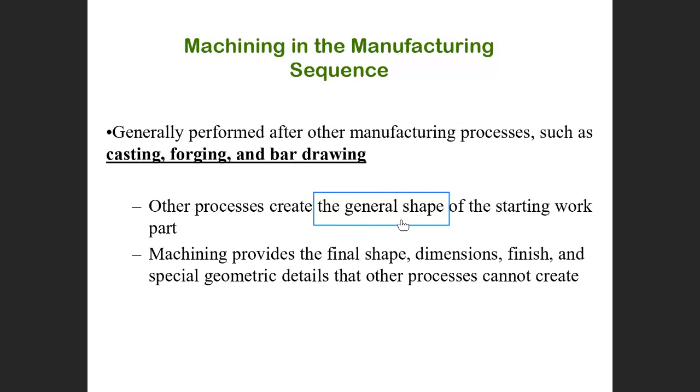Why? Because in casting you melt the material, and shrinkage makes the geometry smaller. So initially we add what we call a machining allowance, meaning oversized. As we described earlier in the casting process, we add machining allowance as a bigger size.